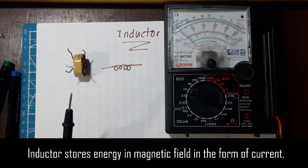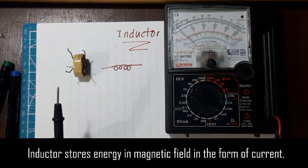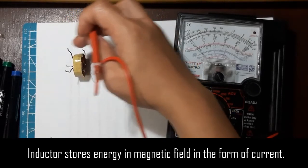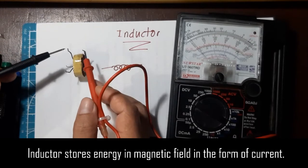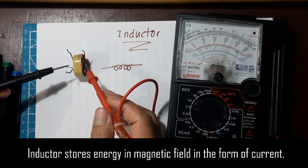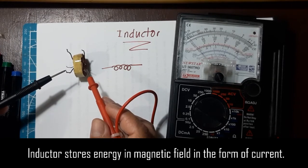Otherwise, we can conclude that there is a discontinuity, or an open circuit, in each end of the terminals. Okay, so to begin, we're going to test this portion, which should give us a low resistance reading. Okay, so that works. That's in good condition. Okay, that's also in good condition.